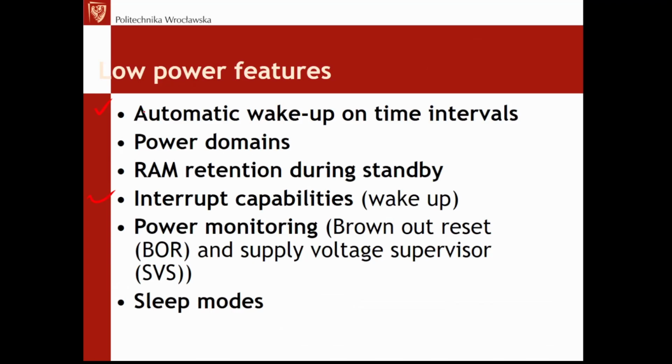Then a quite important feature, maybe not as popular, but still pretty nice and gaining popularity, is power domains. In a microcontroller, power domains mean that the peripherals are gathered together in a few groups, and the groups are sometimes sharing a power supply.